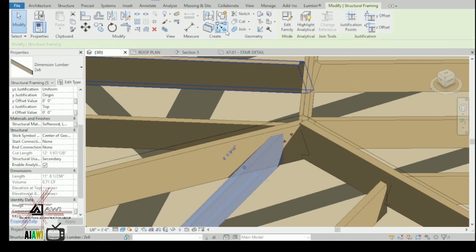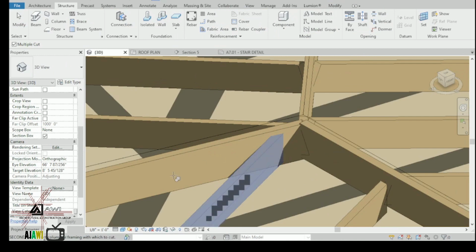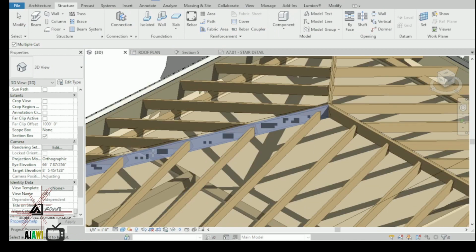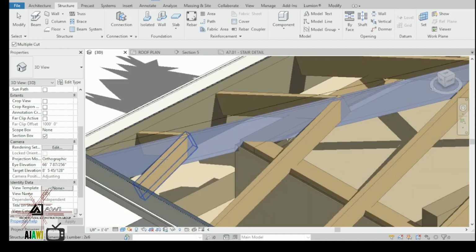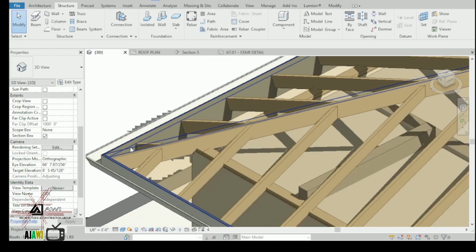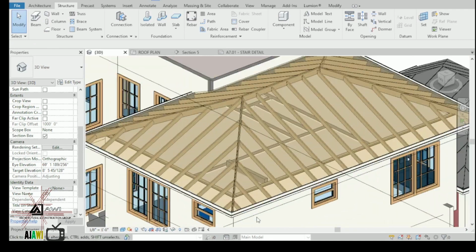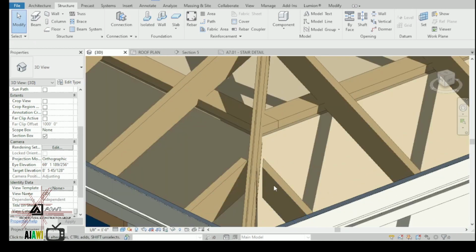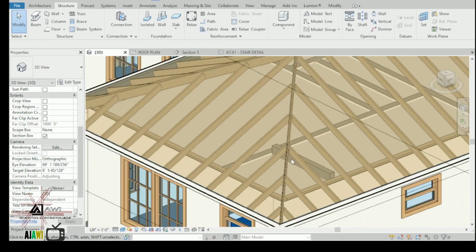Now we're gonna do the notching tool for these. We click on the rafter, and then we use the notch tool. I click this one, that's what I want to cut, and then I'm cutting with this, and then I just click the rest of them. And I'm down here, and I cut. Now there's a space between it. That's a little bit offset. This should be 0, which would make it touch.